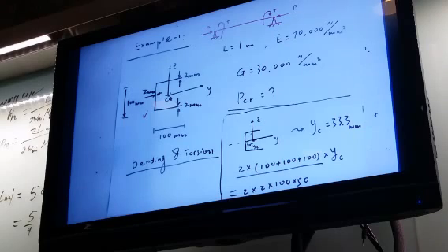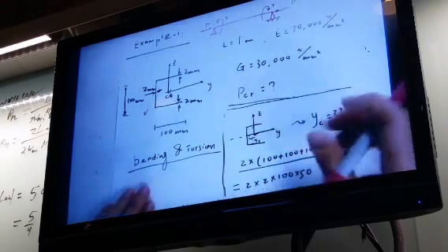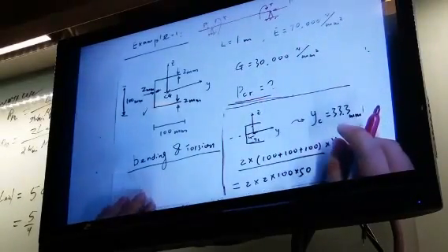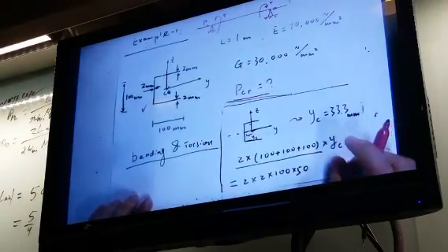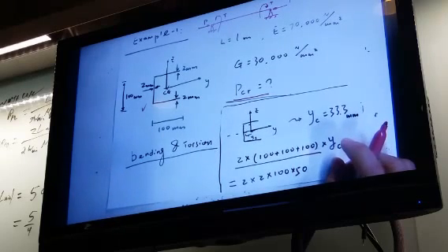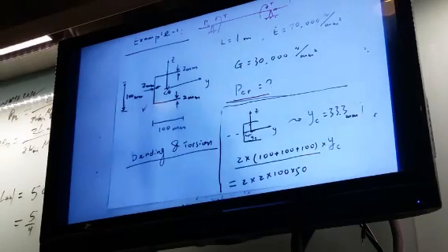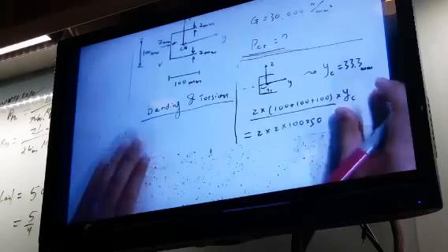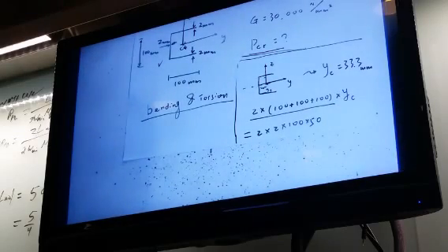Okay, you did one of these problems in your homework. And in this setup, you need to figure out what is the critical loading for buckling to happen. You need to calculate different loadings along the XY plane, XZ plane, torsion plane, and then make the determinant to be 0. You can calculate another P and calculate what is the minimum buckling loading to happen.